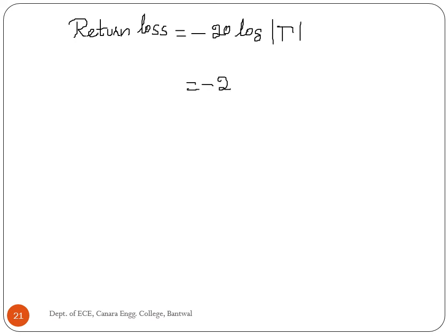Return loss is equal to minus 20 log of reflection coefficient, which is equal to minus 20 log of 1 by 5, is equal to 13.98 dB.